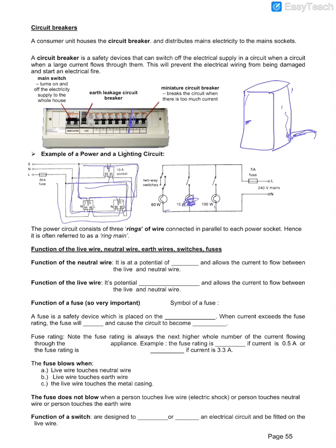In a series circuit I also can get them to have the same brightness, but this one I require only 240, this will be 240, 240, 240, right? If they were all in series and each one of the lamps was 240, my supply would have been 240 times 3. So that's why parallel circuits for lights are required.